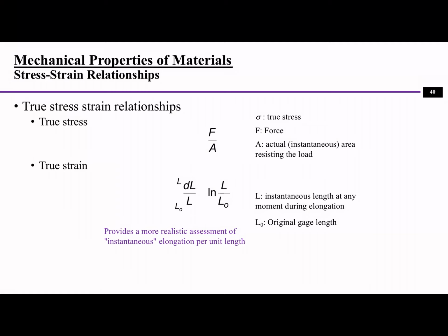Well, some of you probably want to ask a question: when we are stretching the materials, or giving this kind of tensile load or tensile stress, the area of the material actually changes, right? It's not always the same area, because the area is going to decrease. How can you use a constant area value for the prior plot of the stress-strain relationship, right?